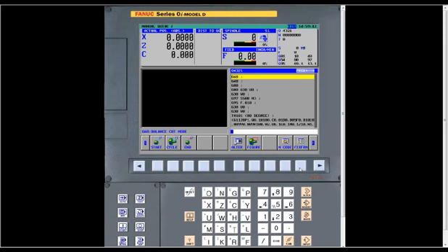You can use a G code to do it, or in your settings you can go in and change it there. But just a further answer to that question, there are some things you have to set up where you have to be in metric mode. Like in probing, when you go in and actually set up the probe, it'll tell you in there that everything has to be done in metric.